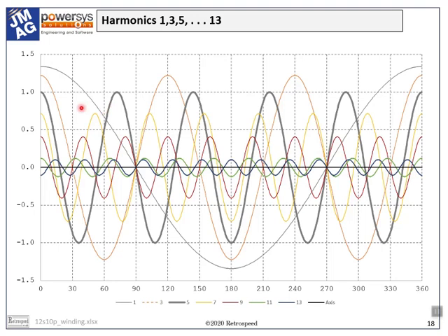So we call this fifth harmonic the working harmonic. All the other harmonics cause parasitic effects such as torque ripple and eddy current losses in the rotor if it has any conducting components like the magnets themselves or a retaining sleeve or even the shaft. The size of some of the other harmonics comes as a surprise. It certainly shook me the first time I saw it some years ago.